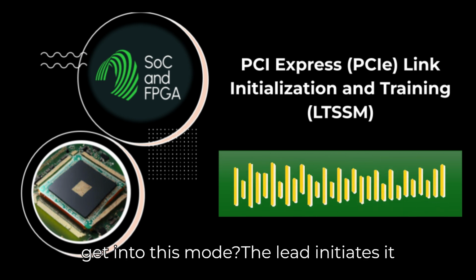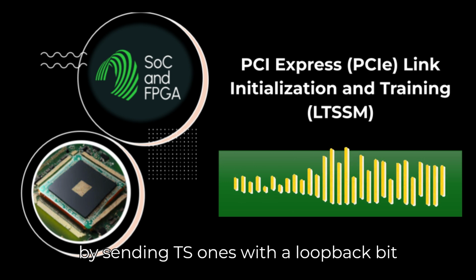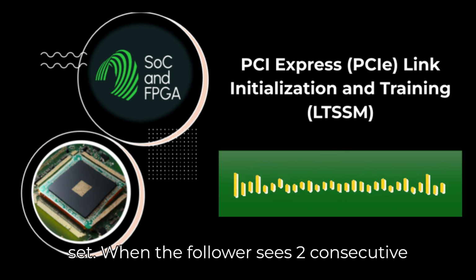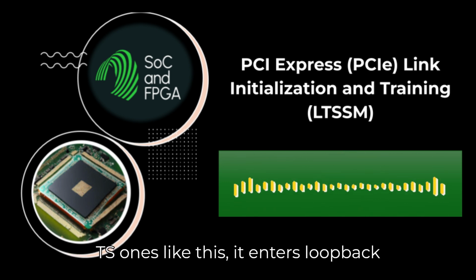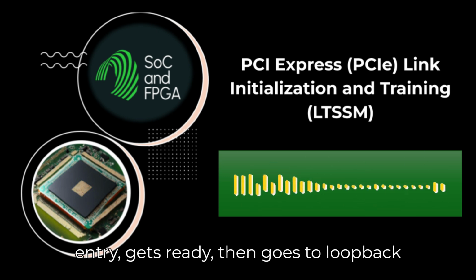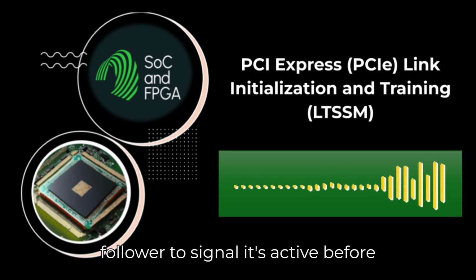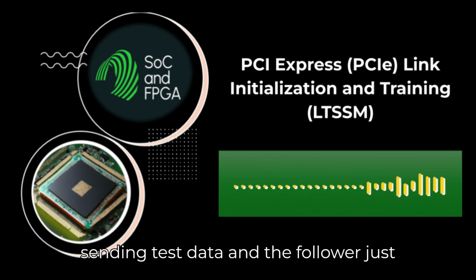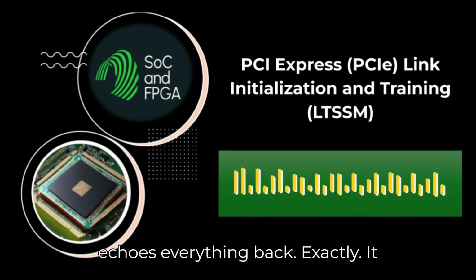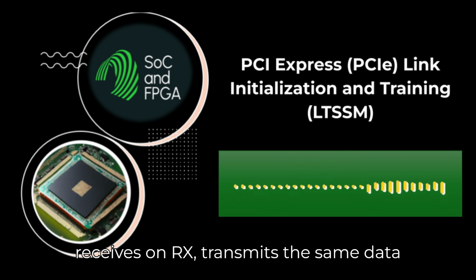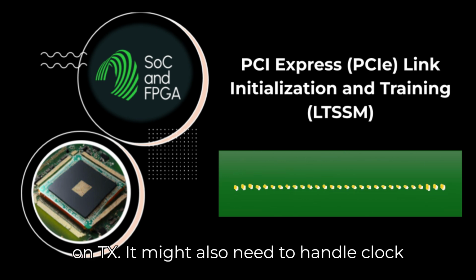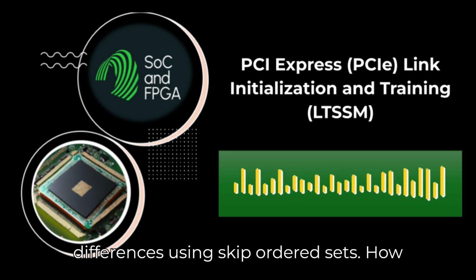The lead initiates it by sending TS1s with a loopback bit set. When the follower sees two consecutive TS1s like this, it enters loopback entry, gets ready, then goes to loopback.active. The lead waits for the follower to signal it's active before sending test data. And the follower just echoes everything back. Exactly. It receives on RX, transmits the same data on TX. It might also need to handle clock differences using skip-ordered sets.